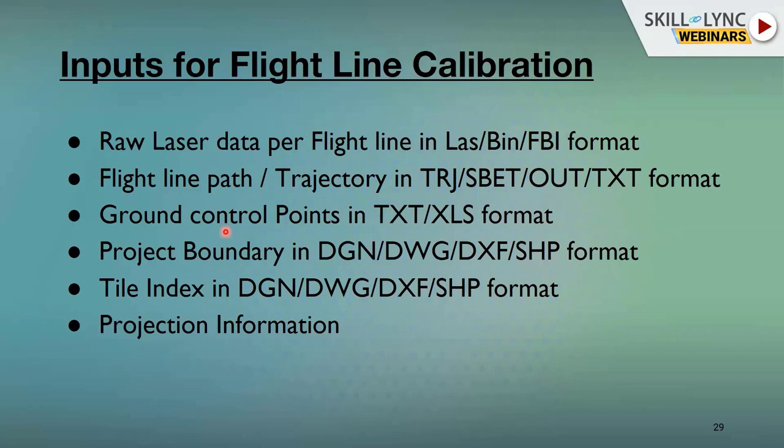They will ask you how you justify that. At that time we can use the control points on the base station points, overlay these points, and tell them this is the accuracy we have achieved. Then we can ask them, if you have any reference points, just provide them and we can show you that. And then the project boundary.